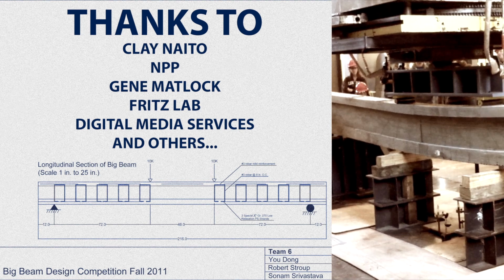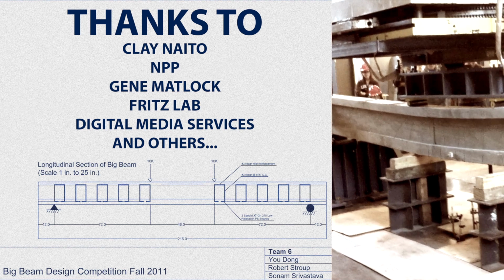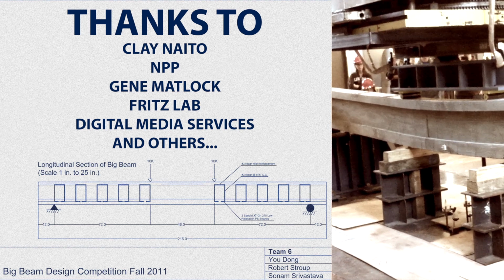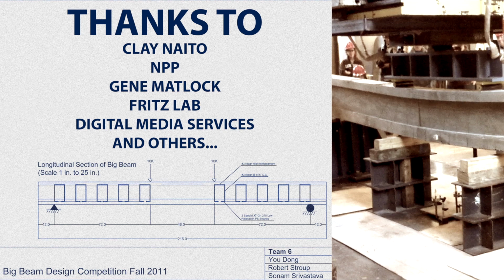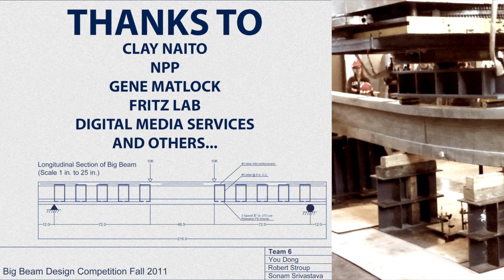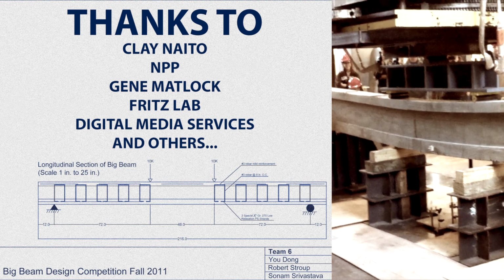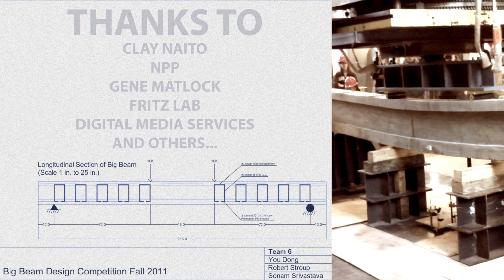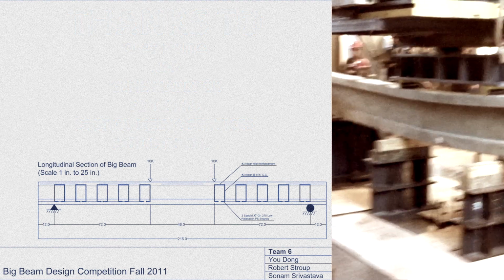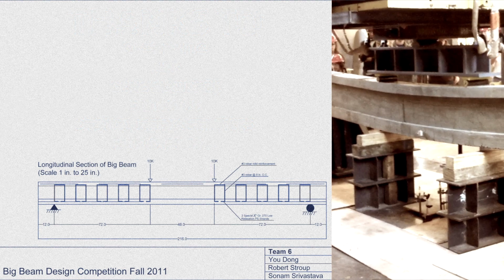Plotting these values over the length of the beam, we developed a formula for determining the curvature of the beam for when the deflections occurred. Our final calculation for the total deflection at the midspan was made by integrating the plot over half the length of the span. This gave us an overall deflection of 3.04 inches.